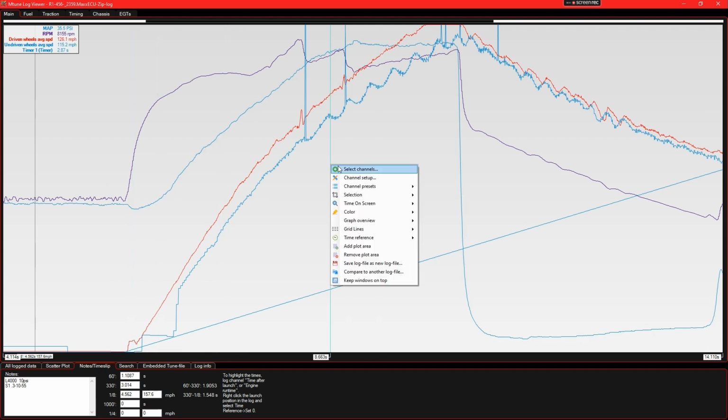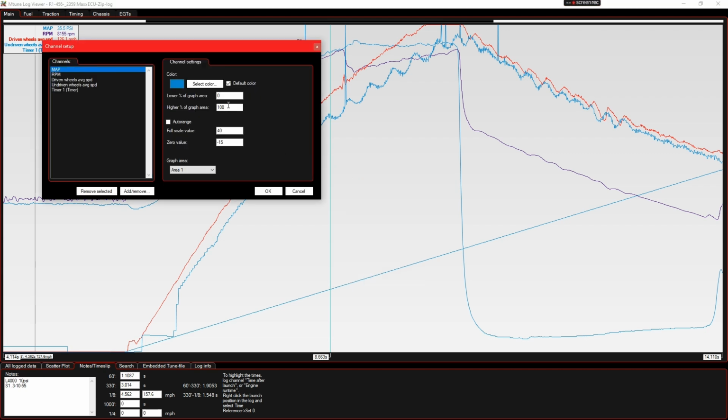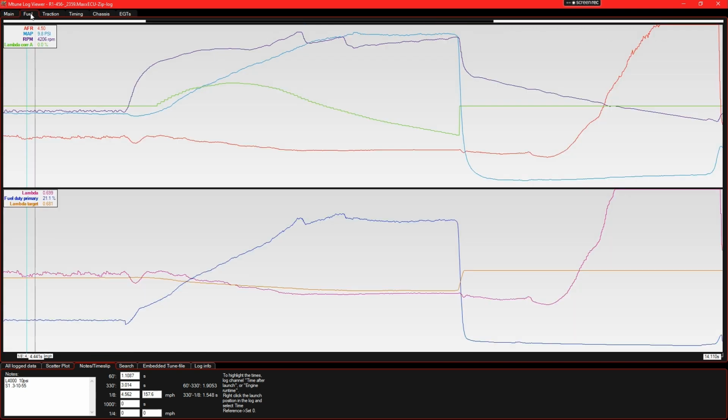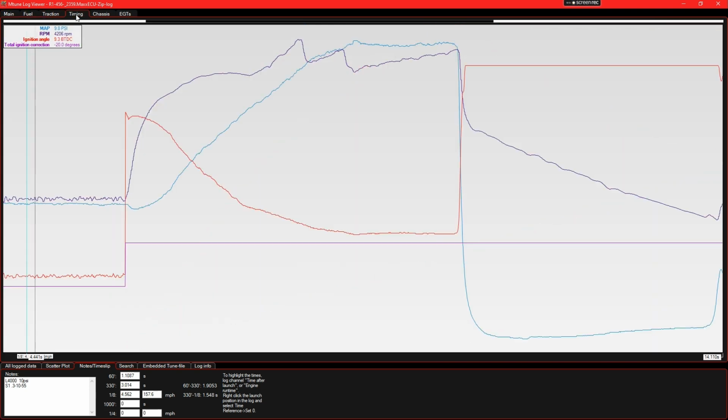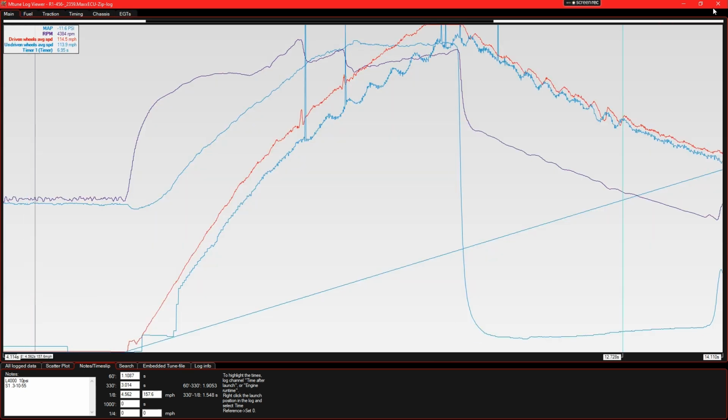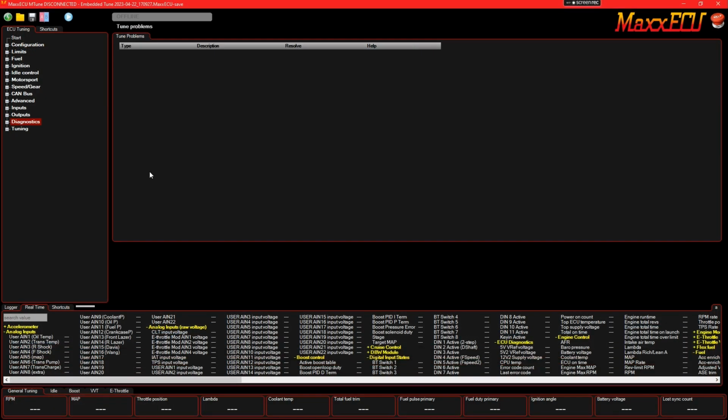And you can really set up parameters on all of your data log, like your channel setups. You can go in here and you can set the range, like RPM range 0 to 9,000. You can just do this on everything. So a lot of cool stuff you can do here. You can even program different folders for different things that you want to see on your data log. But anyway, that was just a quick rundown. I just wanted to run down just kind of the basics of the system without getting too complex with it. But so much stuff you can do.